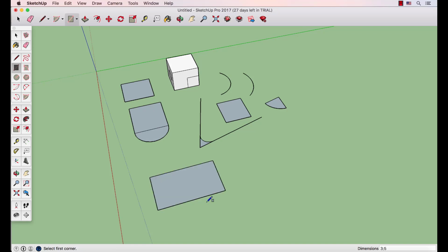In order to draw a circle, we select the Circle tool from the toolbar, we click to define its center, and then we pull and click again so as to define its radius. We can also type its radius in the measurements box, since we have defined its center.